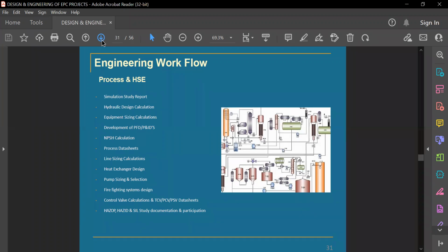So breather valve, so breathing will be done. So in the tank, the pressure will not be allowed to increase. So all those things we have to explain to them, and if the complete team, like the assembly of people sitting over there, are satisfied, then we can go ahead. Otherwise they will say that okay, you have to put one safety valve on the tank, or maybe one more breather valve, or maybe a rupture disk you have to put over there, or maybe another transmitter to be added, in case this one fails. So these are the things which come under HAZOP.